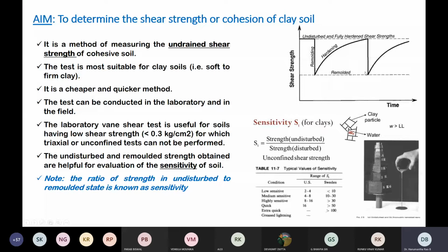That's it. Then place the specimen container on the base of the Vane shear apparatus. This is the base pedestal of the Vane shear. Put the container with the soil, then lower the Vane into the soil sample. This schematic diagram demonstrates the minimum lowering depth. When you lower the Vane into the soil sample, this is the soil sample and these are the Vane blades.